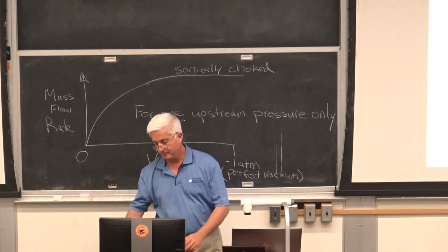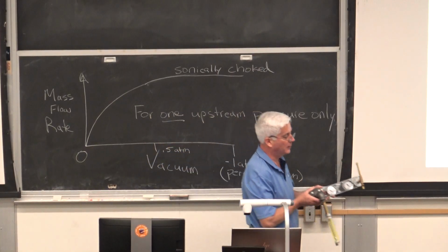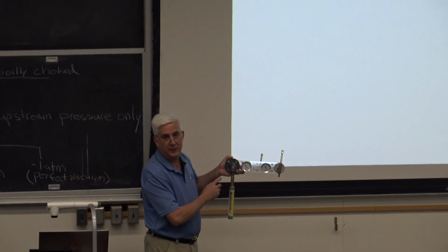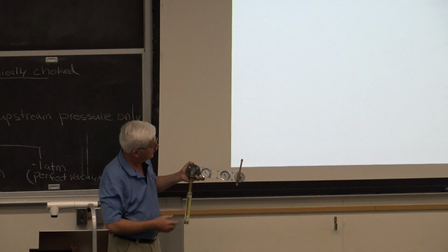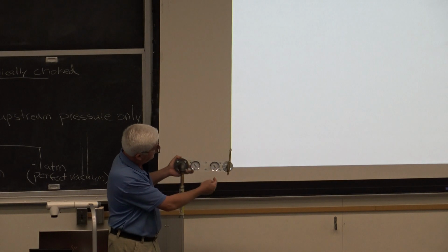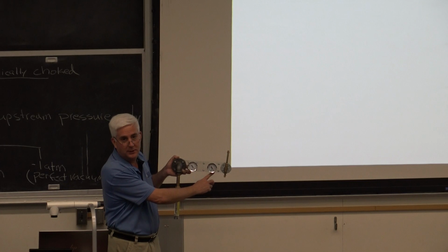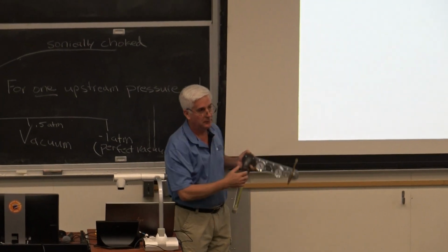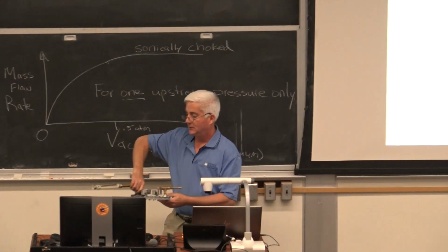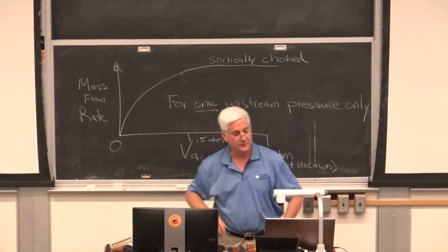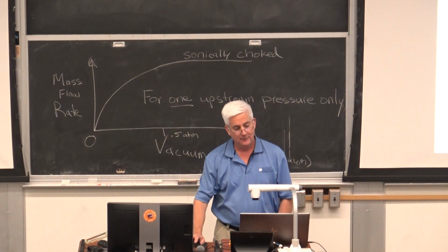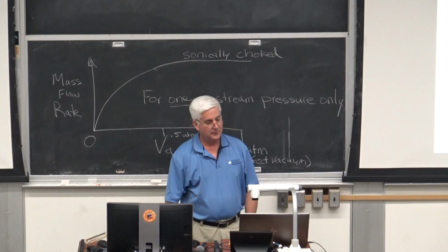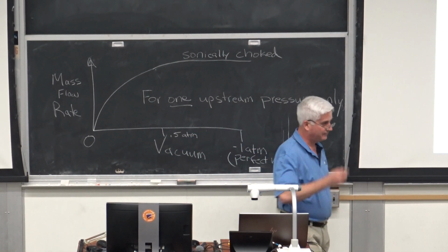So in other words, if I take this little gizmo and I've got 14.7 psi atmospheric pressure on this side, if I drop this side to roughly 7 psi, I'm at Mach 1, right in that opening. I always thought that was pretty snazzy, that it worked that clean. So of course, I had to go try it.